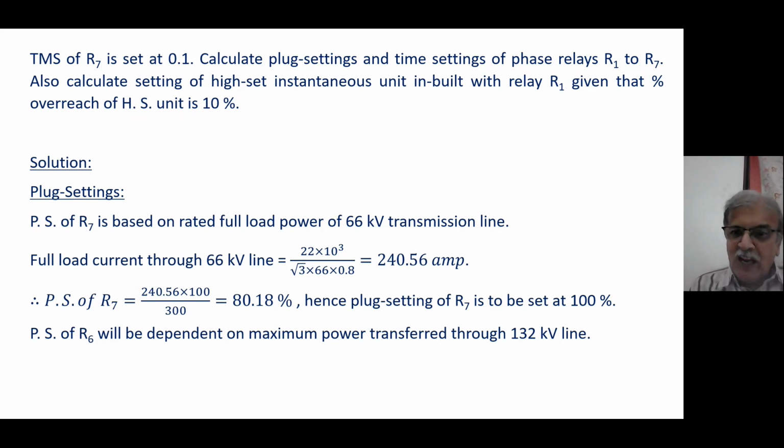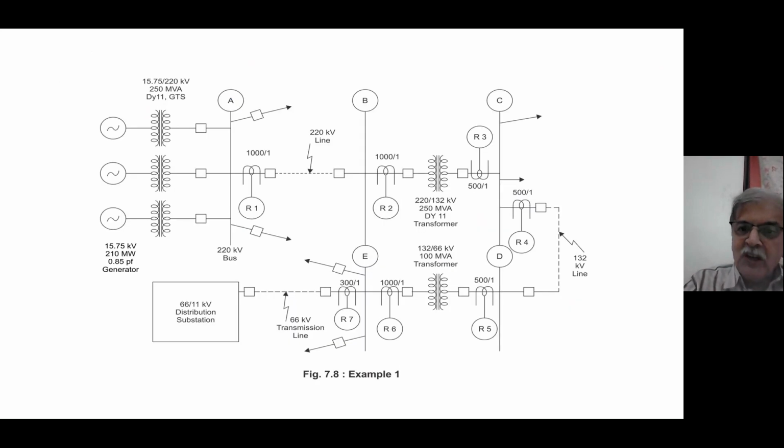Now for R6, what do I have to do? For R6, my dear friend, I have to consider that it is taking the full load current of the 132 kV line as seen on the 66 kV side.